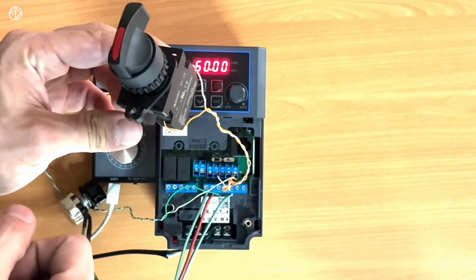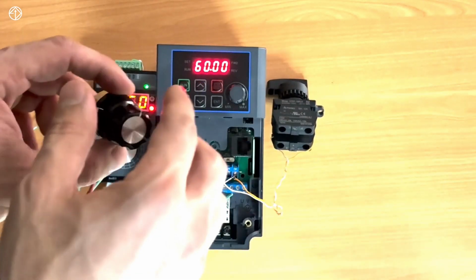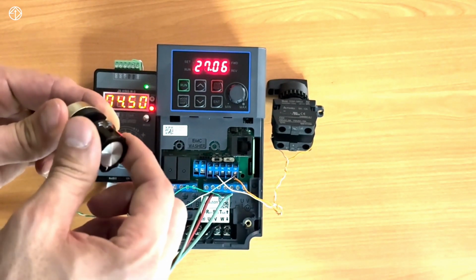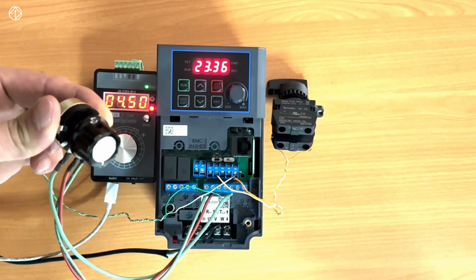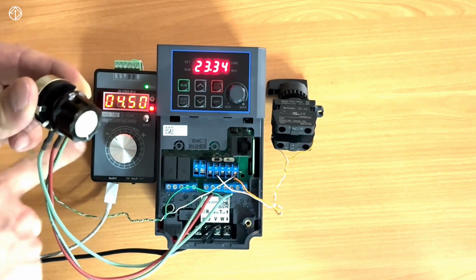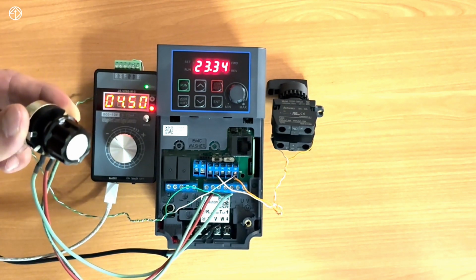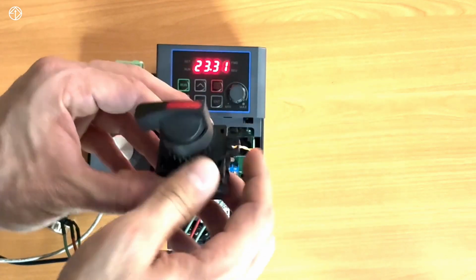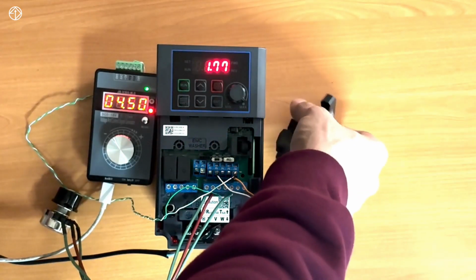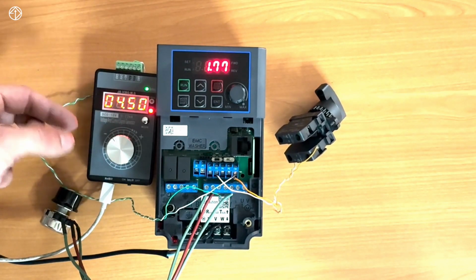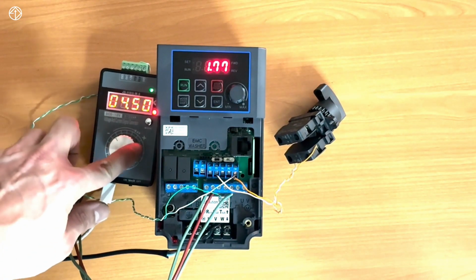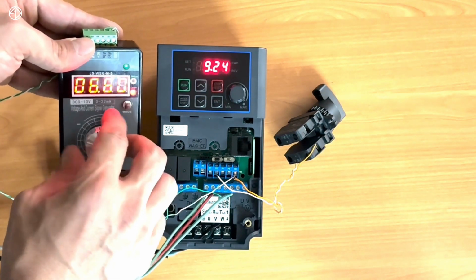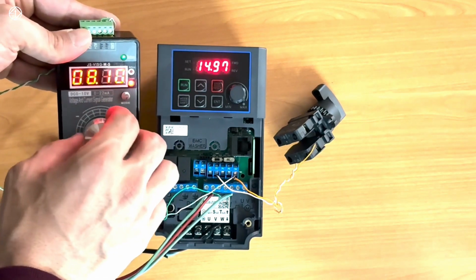Right now, my digital input is inactive, so it's in local mode. If I adjust the potentiometer, you can see that my frequency changes. This is the local mode. Now let's say I have another operator or another section where they want to change the frequency using a current module, or I have a 4 to 20 milliamp 2-wire sensor. I activate my remote mode, and as soon as I do that, by activating my sensor, it switches to current mode. Now, as I increase the current value, you can see that as I increase the milliamp value sent from this device, my frequency value changes.